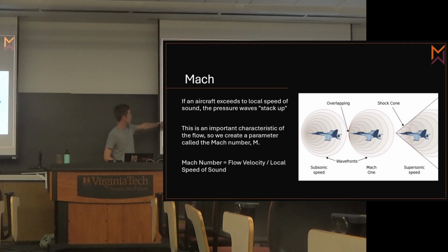And then the big thing is, when we get to high-speed flow, it's interesting because at low speeds you're always dominated by Reynolds number as your main factor. Exactly, the velocity is changing relative to the viscosity of your fluid, and that's your big condition for what your flow looks like. Once you go really fast, especially hypersonic, past Mach 10, the Reynolds number of the fluid just does not matter. The only thing is Mach number, and that's it, because it defines the angles of all the shock waves and how pressures and temperatures are increasing, which we'll talk about.